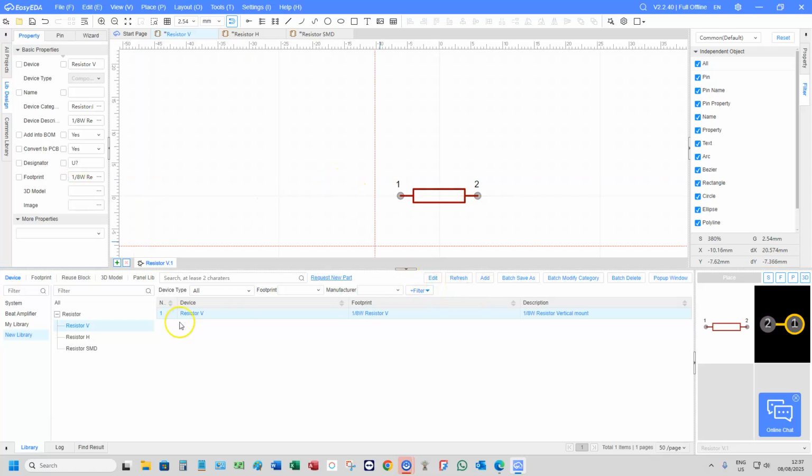And this is what you would do if you were going to do capacitors, for instance. They can be mounted vertically or they can be mounted horizontally. Transistors as well. You can have diodes, the same. But it's imperative that you have the symbol linked to the printed circuit board device, or the silk screen, so that when we transfer our schematic to a PCB, we get the correct mounting.